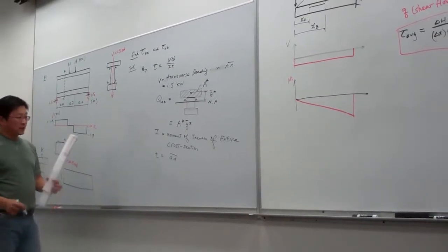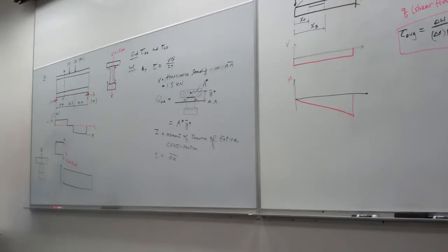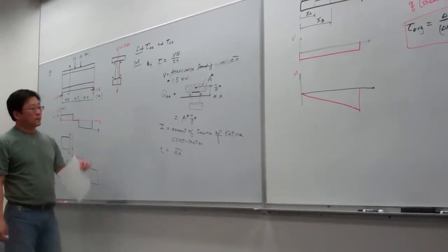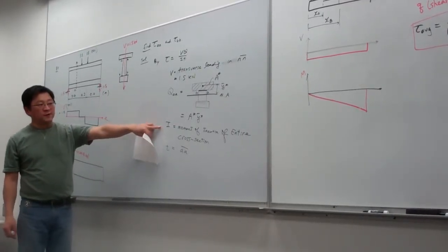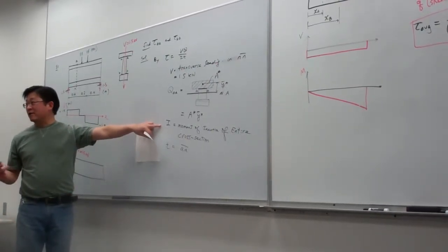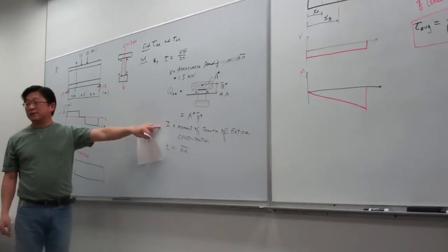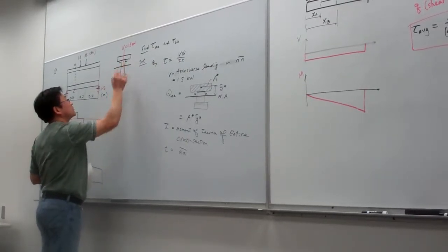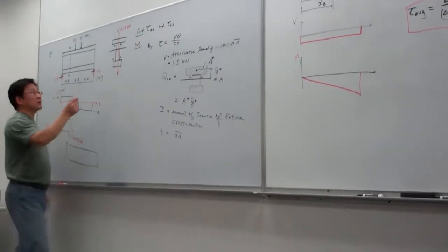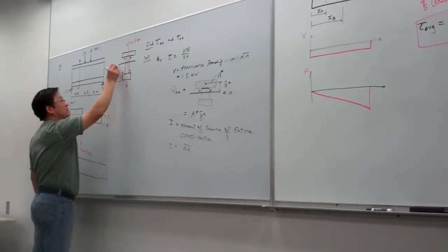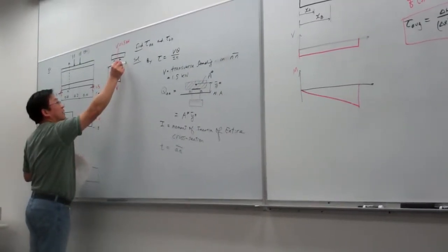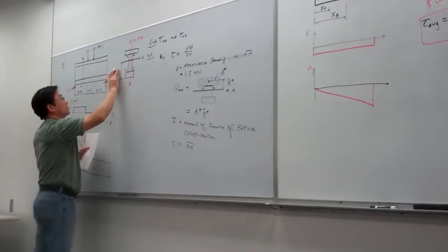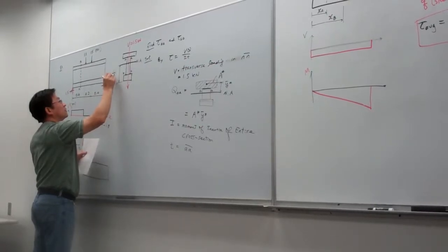So for this case, let me pick up the numbers here. To calculate the moment of inertia, you have to follow chapter 4, and the really time-consuming part is determining the centroid or the neutral axis. Let me skip the details. For example, let me directly give you the neutral axis, which is 68.3.